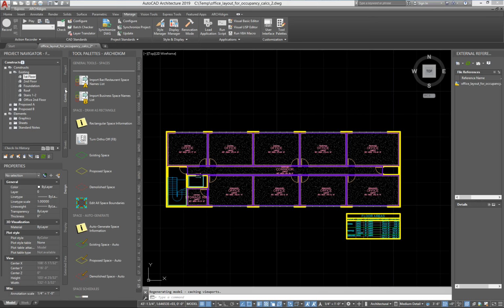So in the previous discussion and demonstration, we left off with the floor plan on my screen, where I had shown that you can use floor slabs if you want as a means to tag and track your areas. You can even schedule floor slabs.